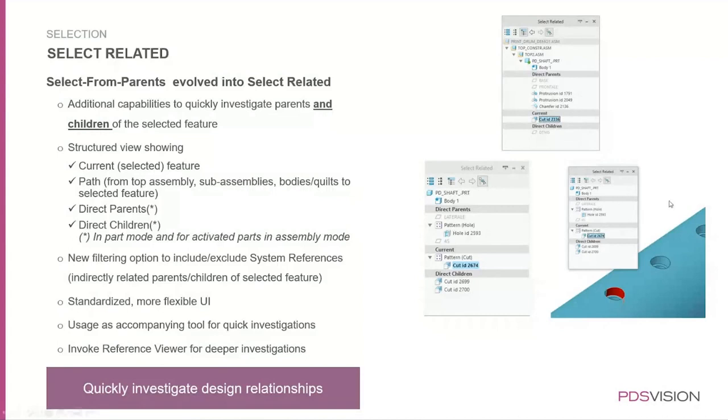If this kind of window is present and you click around, the current selection will always automatically change and update, and the corresponding features in the model tree are also activated. But if you start clicking from here, on different features, they don't change the active selected one. These are just selections for the features.